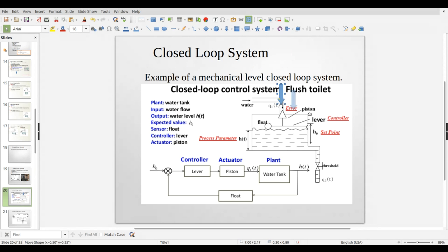What happens is when you drain this, so you open this up and allow the water to leave, then the lever for the float, the float drops, which pulls this lever down, which of course allows water to return into the system. And then as the water level rises, the water slows down, so you don't let in as much water, right?